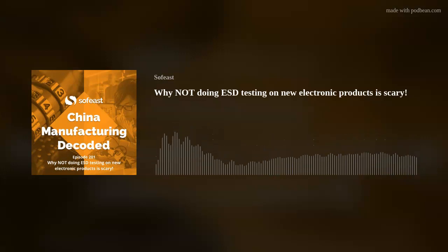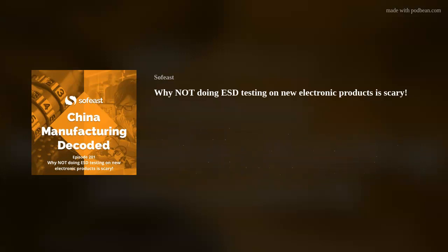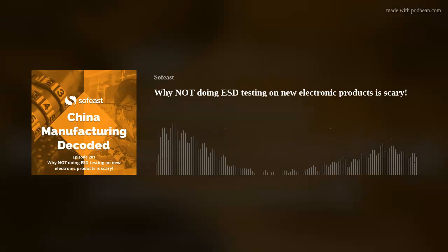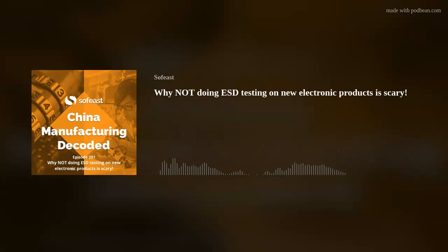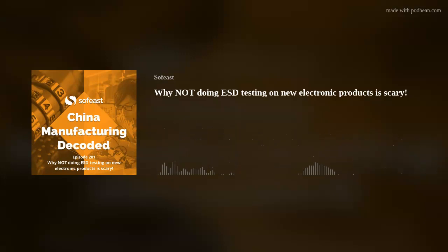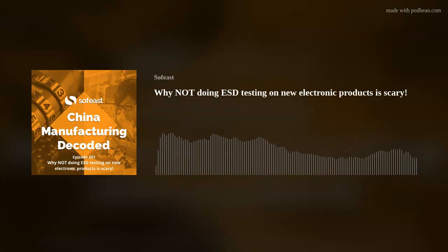And of course, as we were saying before, a lot of these have been designed in a way that they're not happening as much anymore, but it's still good to know these things as a designer so that you're checking and making sure you have a protective element for your product and your design towards ESD. Some of the advantages of this one is that it really mimics and checks your real manufacturing ESD issues. Compared to the human body model, this one has a faster discharge time and can identify vulnerabilities in automated production processes. Those are some of the good advantages.